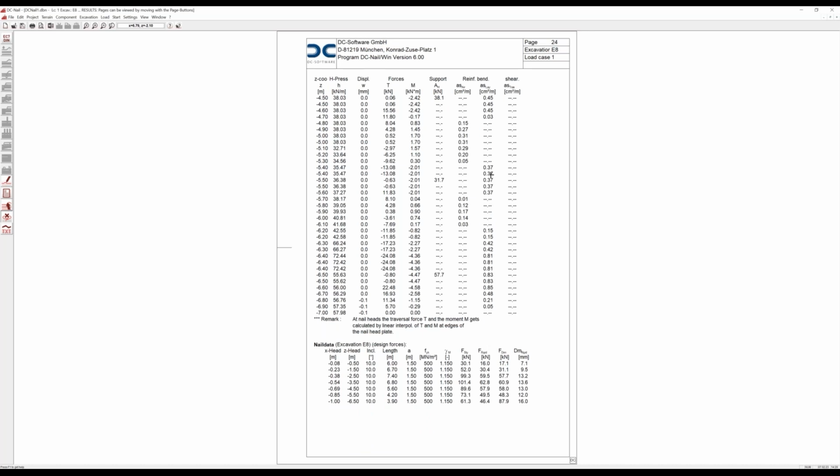And then we have different nail forces, and we have to use the critical ones, which means we have first a nail force which might be possible. So if a soil nail is very long outside of the critical block, it could transfer very high force to the ground. But this higher force is not always required. So this is the possible force.